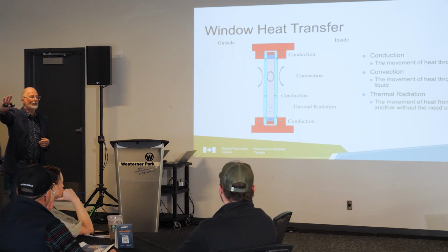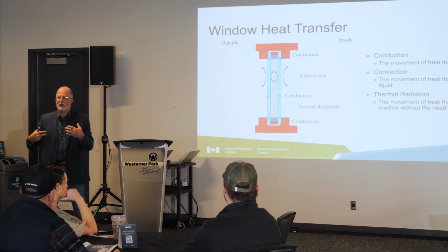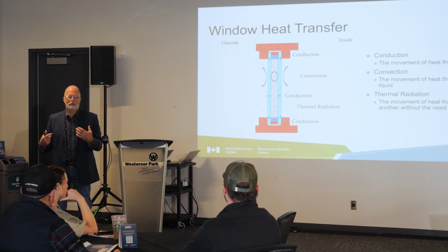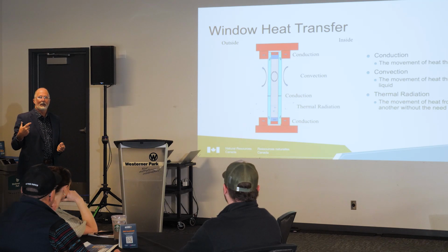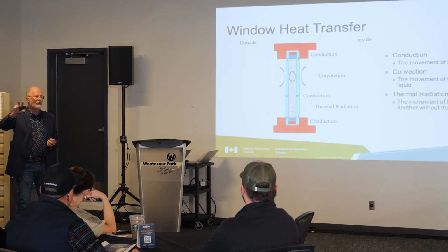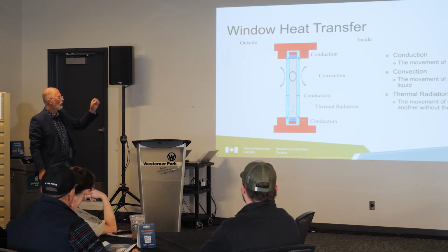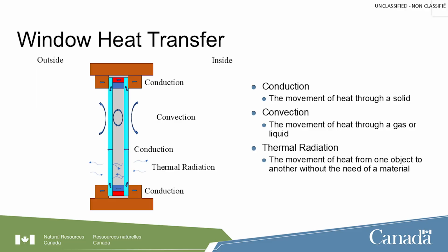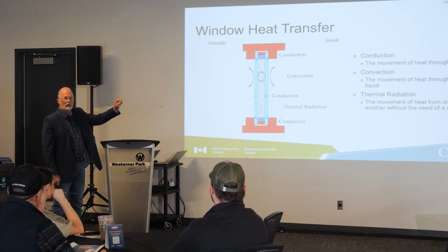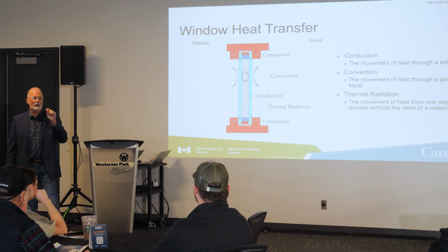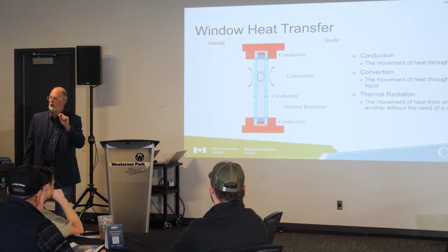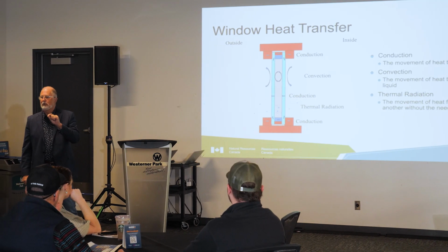But if that's a hot surface, if that's a fireplace, am I standing beside it? Which way is the heat transfer? It's from the fireplace to my body and it feels warm. So the reason we feel cold in a house in a lot of cases is because that surface is the coldest surface of the house. So thermal radiation. When we transfer that thermal radiation through, we can do things to a window to adjust how much goes through, which is what we call solar heat gain.